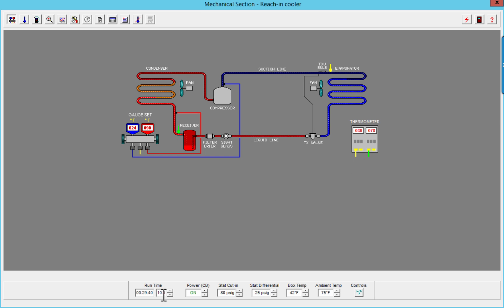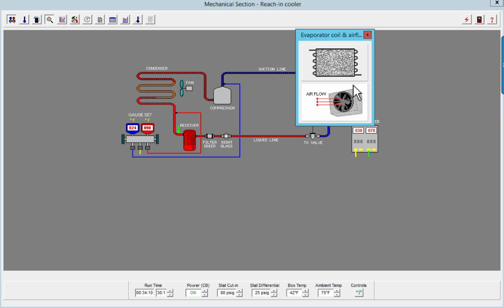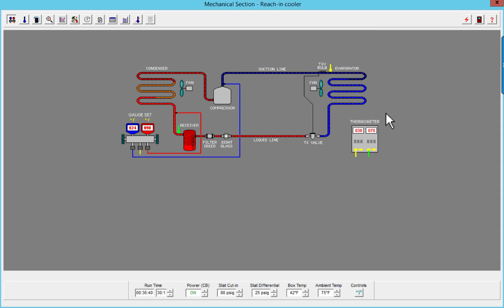Okay, and the longer this runs, the more ice is going to form on that coil. So, what do we have going on? I have a system that has a 6-degree superheat, should have a 12-degree superheat, or at least 8 to 12. I have a high side temperature that's now 90 degrees with my 75 degrees.